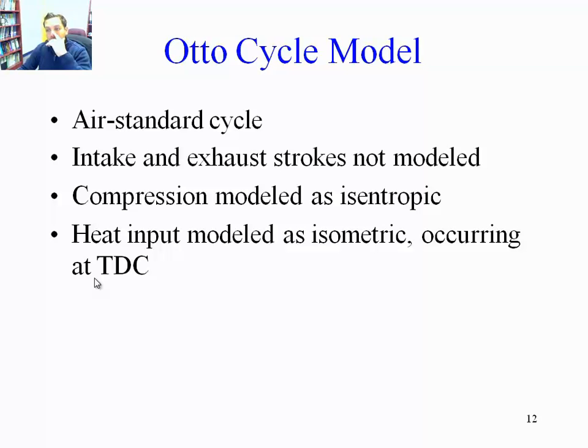So the process of heat input, which is the process of combustion, usually from the thermodynamic point of view you conceive as heat exchange from an external source, basically a hot temperature reservoir. But that's not what happens in an internal combustion engine. That's why it's called internal combustion, because there's internal heat addition, because the air is mixed with fuel. As the piston moves up, the volume of the cylinder shrinks. That's the compression process.